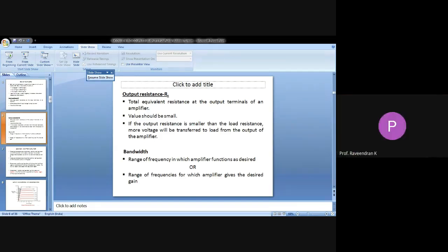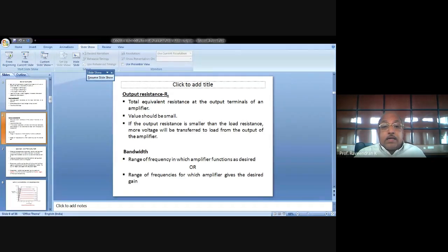The transistor beta is always there, but that should not have a direct linkage or connection with the operating point. The operating point and the operating region of the transistor must be such that it should not depend upon the parameter beta. Of course, the input signal will be amplified with the corresponding gain available with the transistor circuit. But the operating point must always be independent of the transistor parameter beta.